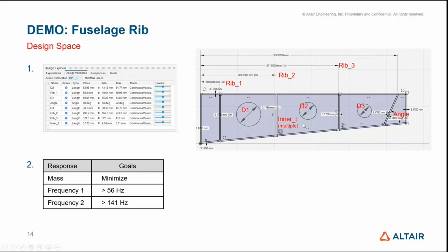But as I mentioned, if you've parameterized your sketch, as this one has been, everywhere you see this f of x or function, a parameter or variable has been defined, and we can leverage it. Just for example, the length from the datum line out to rib 1, this vertical rib, is parameterized. It's got a nominal value of 50.8 millimeters, and as that changes, this rib slides back and forth, and rib 2 and 3 and so on, and then the diameters have been parameterized.